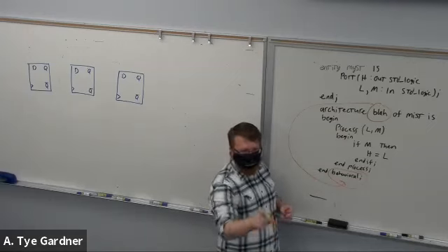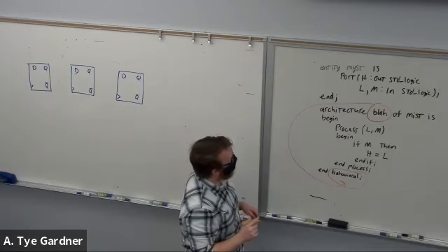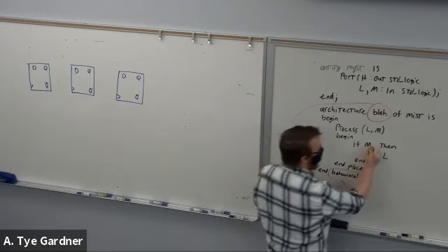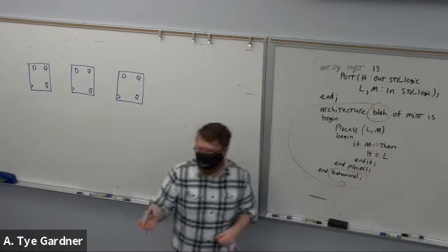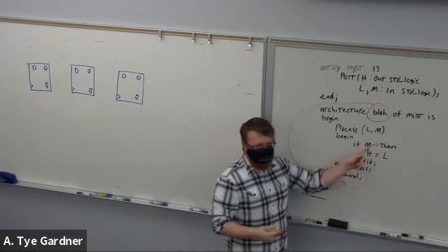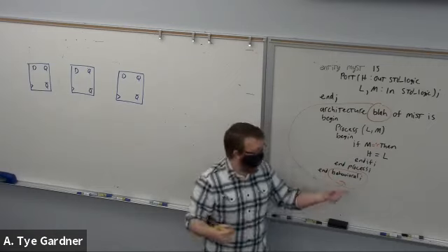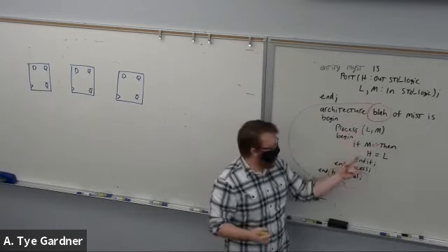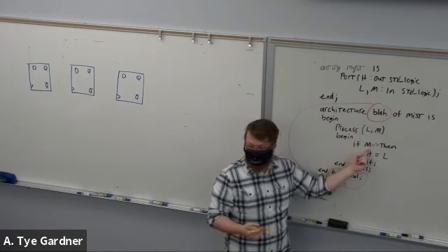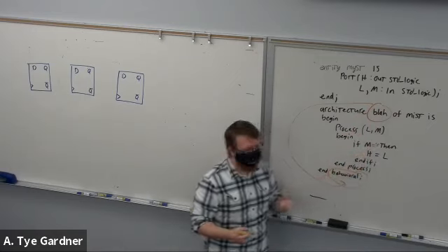What else have we got? In your if statement, shouldn't it say if M equals something? Yes, if M equals 1 or 0. If you said either one, or even just said, hey, this is a problem, unless I ask you to fix it, because M is a standard logic. If M was a bit type, this is fine, but for standard logic it doesn't work.